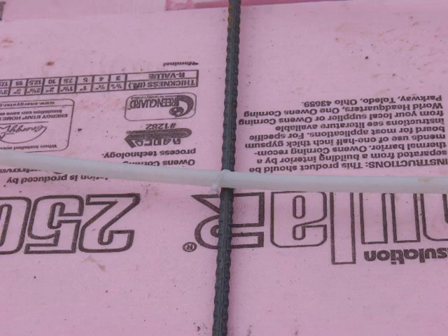The reason this is important is if you come back later and do some saw cutting, or like we said, if you have walls that you're nailing down, and let's say someone comes back at a later date and wants to remodel, and they shoot down with nails their new walls into the slab, the more concrete you have between the top of the slab and the top of your piping, the less chance there will be of damaging these tubes in the future. That's a very important detail to keep track of.